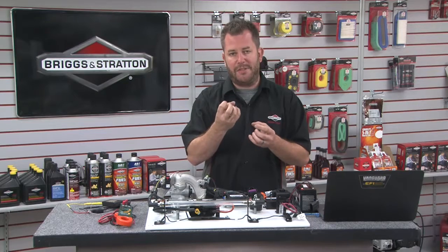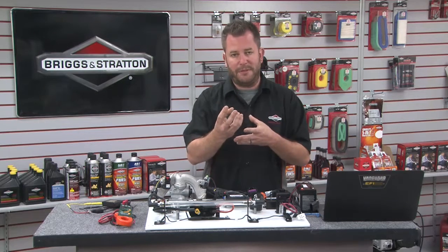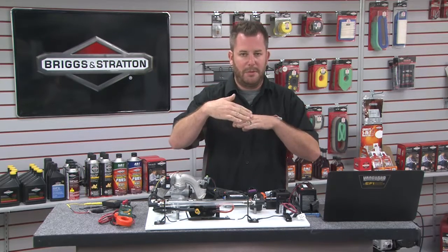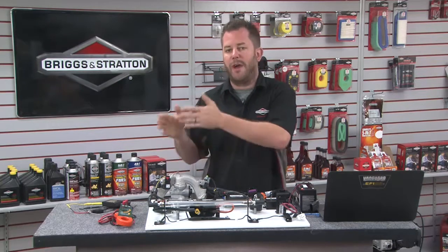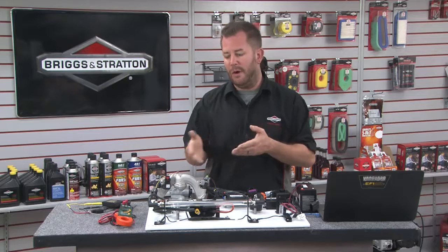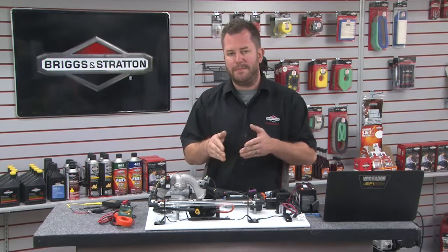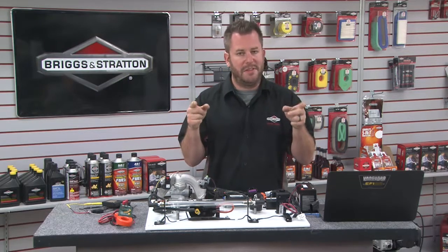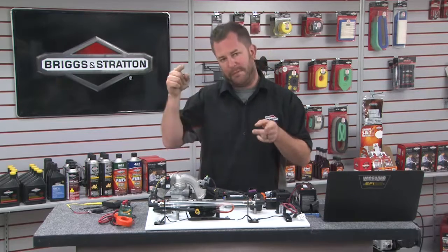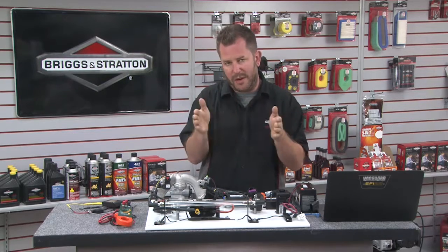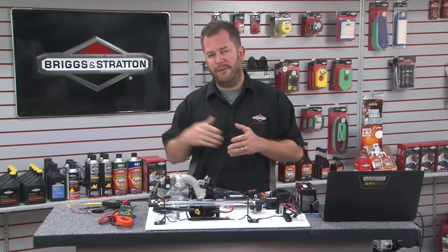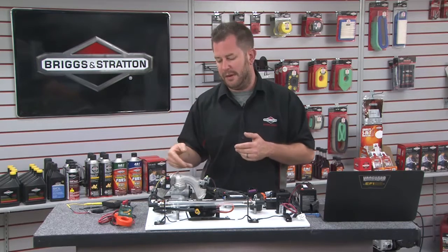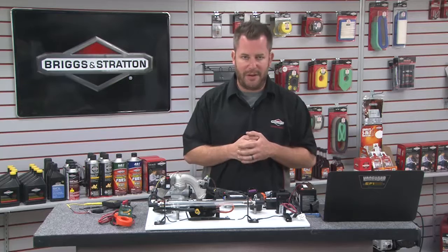And of course, as the thermistor reports a different temperature change, really what's happening is the resistance varies, which basically affects a voltage drop coming back to the computer. So we send 5 volts into it, and it needs to operate within this range of 0.5 all the way up to 4.5 volts, anywhere in that window. Now, what it's telling us right now is we've stepped above 4.5 volts on the return side. And when we test this out here, we'll be able to verify that.